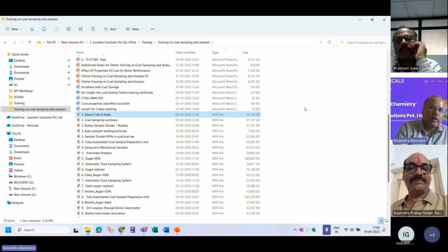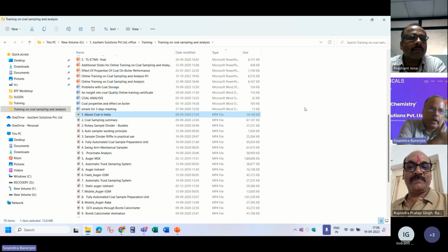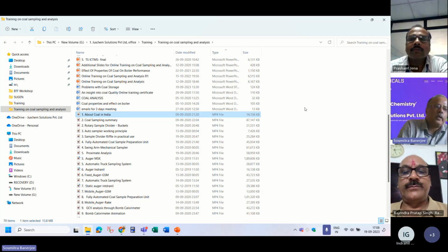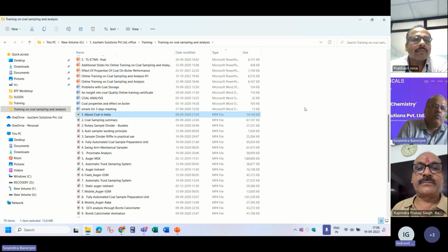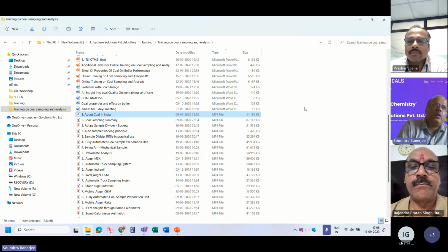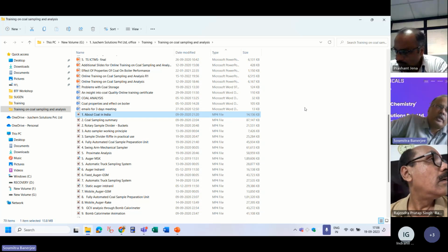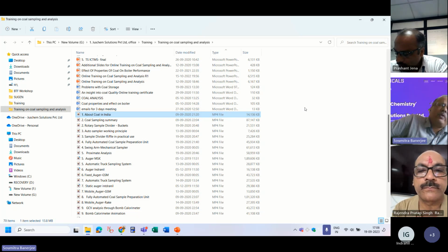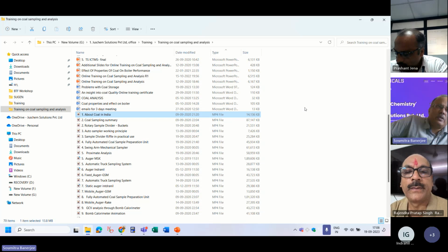I was not knowing 100% about which coal is being used, so I took everything in the kitty. But Indranil, frankly telling you, whenever we sprinkled water in the coal and the surface moisture increased, and when we do the moisture corrected GCV, at that time we find a little bit of difference, maybe 1.5% difference in GCV.